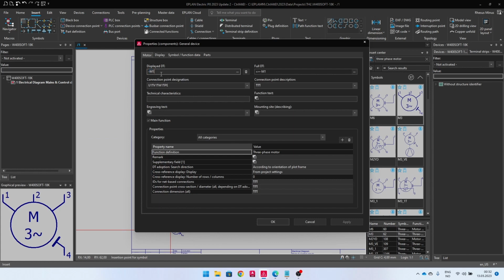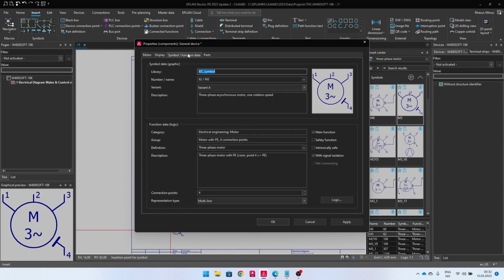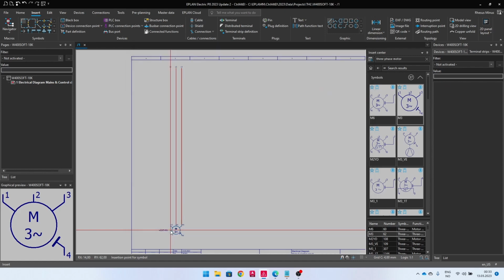And also this motor, it is not part of my project, so I will just keep it externally. So I can of course say plus EXT, just like I did in AutoCAD Electrical, but in EPLAN I can also say that it's actually an external component. So by tagging this as an external component, it will not be part of my part list in any way. All cabling, all connections going to it will be reported, but the actual device will not be reported.